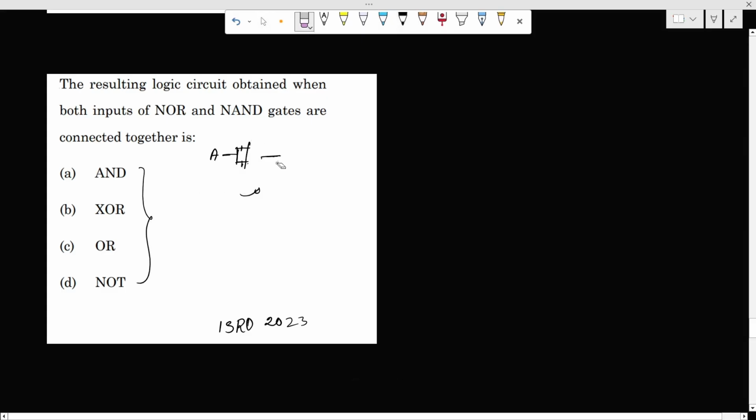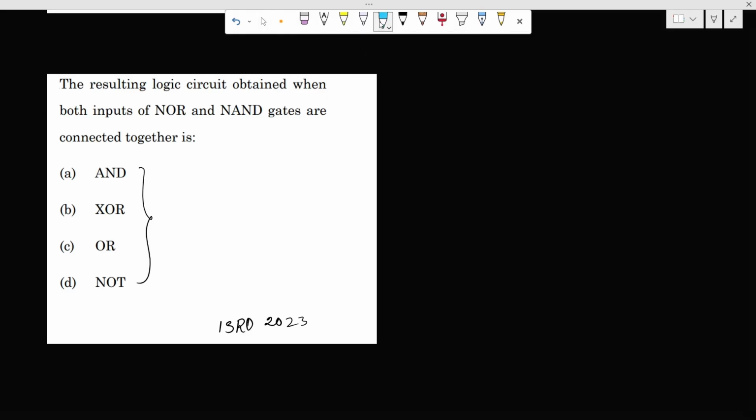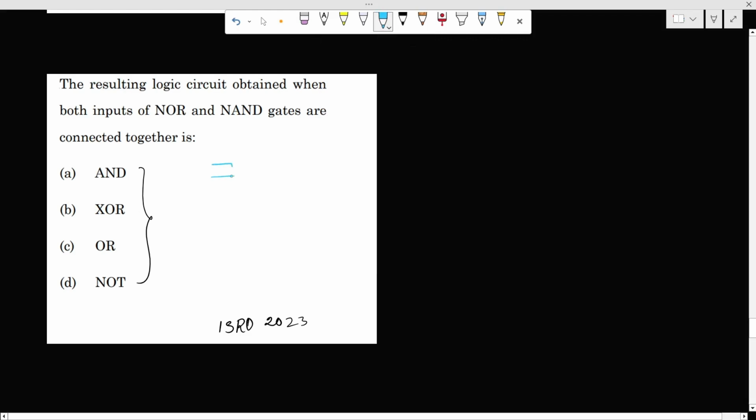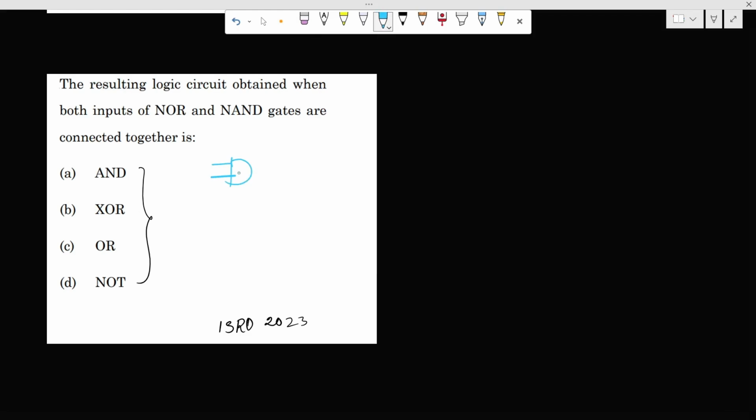So basically, at first, for the NAND gate, we have to see that if we get A here, this is basically A, this is basically A. So NAND produces A dot A whole bar. As A dot A becomes A, it produces A bar. So when both the terminals are connected in inputs, it produces the complement of the input. So it works as a NOT gate.